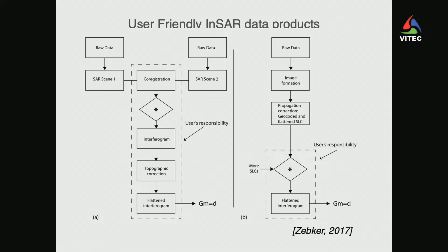So what you really need to do remaining, as the user, is load these SLC images, take the conjugate of the second image, and do a piecewise multiplication. That's your interferogram. And you can apply any filtering you want. The phase unwrapping is a standalone routine. And so with that, you could start to do the deformation analysis on your own.